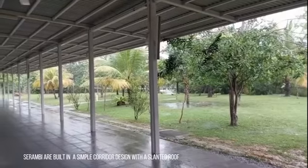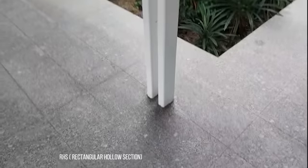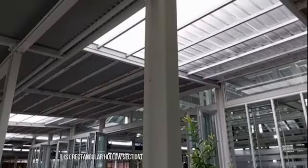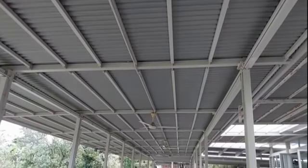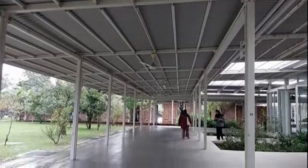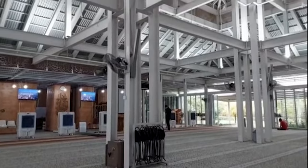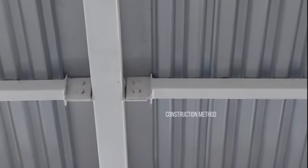Following that, the Serambi are built in a simple corridor design with a slanted roof to cover it. The column used is RHS, which is rectangular hollow section in the size of 100 x 50 mm with a span of 6.5 meters column to column. To create a stable and efficient structural system for Masjid Cyberjaya 10, various types of joints and connections are used to assemble the structural members. The choice of joint and connection type depends on factors such as the type of structure, loads it will bear, architectural requirements and construction methods.